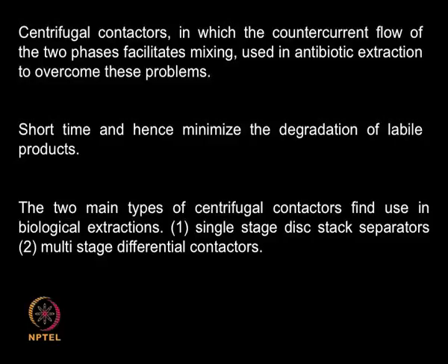That means the higher density liquid will reach the walls faster because of the centrifugal force. So the walls will have predominantly higher density liquid, and the lower density liquid will be more in the middle portion. So centrifugal contactors are another way of separating out these two layers instead of resorting to settling based on simple gravity.